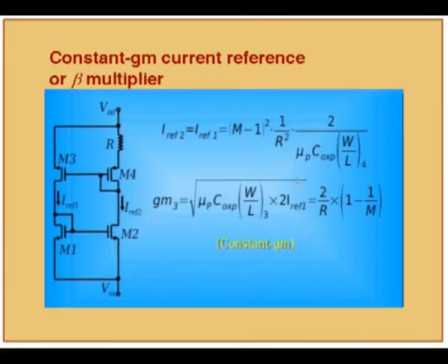And actually this is one of the main bottlenecks. If you could achieve a very almost constant R on chip, then we would generate very nice current reference generators, because we can get rid of these parameters. But this R always generates variation in the reference currents.